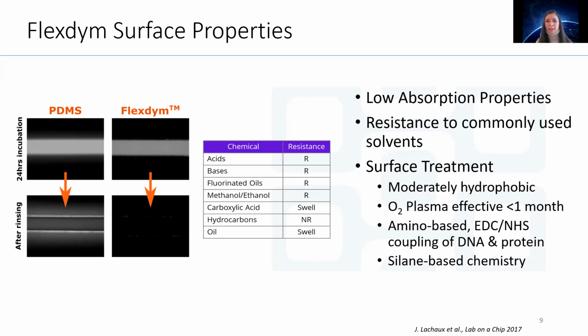We've also done tests to check that Flexdym is resistant to certain solvents that are commonly used in microfluidics. So for example, fluorinated oils that are used for droplet microfluidics, and acids, bases, methanol, ethanol. Now we do see some swelling for carboxylic acid and other oils, but this is typical of many of these materials that are used for microfabrication of microfluidic devices.